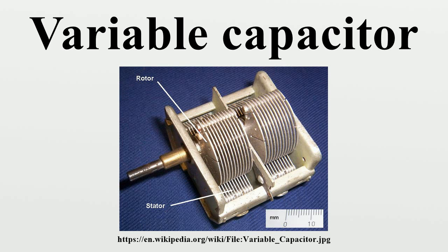Digitally tuned capacitor. A digitally tuned capacitor is an IC variable capacitor based on several technologies. MEMS, BST and SOI/SOS devices are available from a number of suppliers and vary in capacitance range, quality factor and resolution for different RF tuning applications.